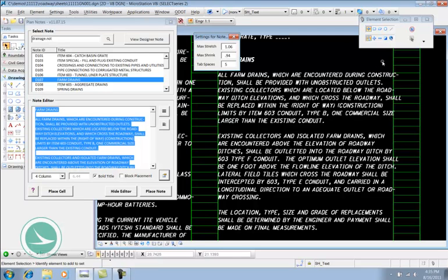Any more than that or less than that, the text starts to get a little hard to read, with some things stretched out too far. You certainly wouldn't want this last line here, larger than the existing conduit, stretched all the way across. So that's where these maximum settings come into play, to help it determine which lines to shrink or to stretch. And you can change those tolerances if you want. I just wouldn't change them too much because, again, you'll start to get some weird scaling.